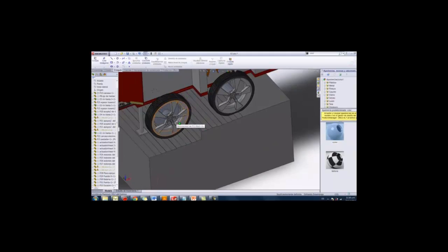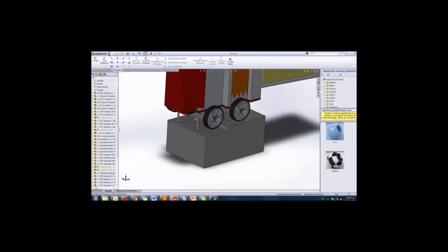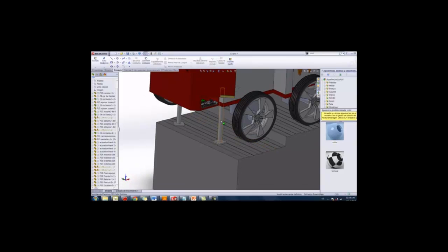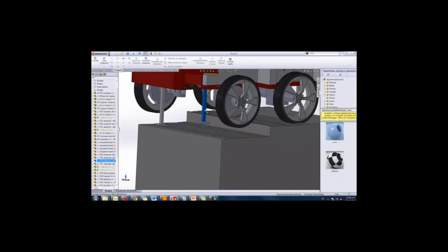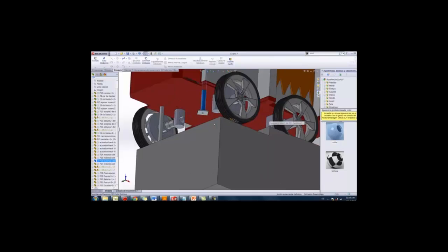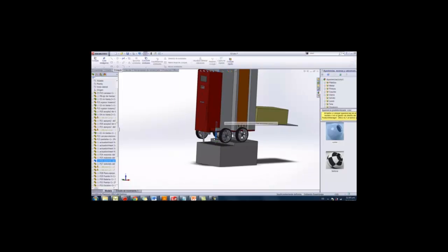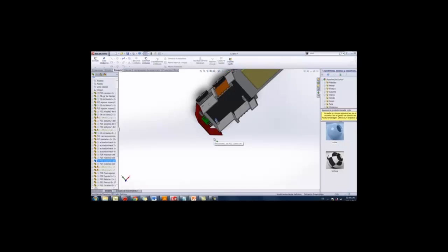About the suspension, the model shows how the robot climbs escalators. The position of the front wheels and the rear wheels will be controlled through linear actuators moving pistons, which are supported on the suspension, and keep the robot in a fully horizontal position. These pistons will have a hole, shown in the animation now, with a piezoelectric sensor that will indicate how much the robot must rise or go down.